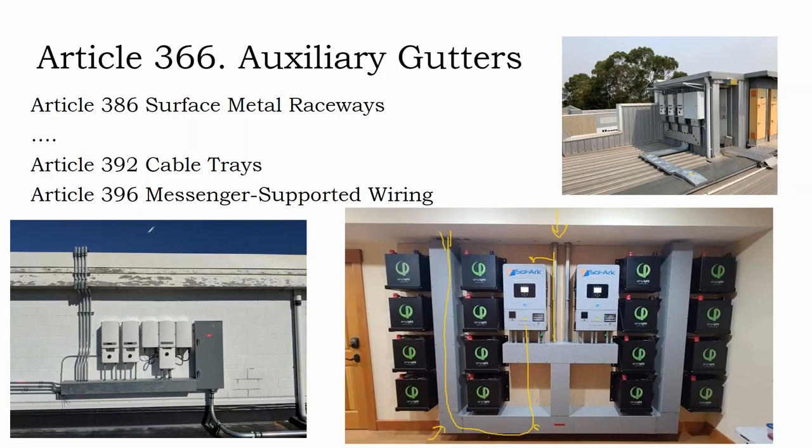So over here on the left, we have 4 EMT runs up to this section of the rooftop, and we have 4 EMT sections running off onto that section of the rooftop. And each one of these sections has to be bent and made up and attached and drilled and knocked out, and then the fish cable put through for your conduit pull, and then that taped off and tied to all the conductors that have to be prepped individually when you're pulling them, so you can pull them through all at once.